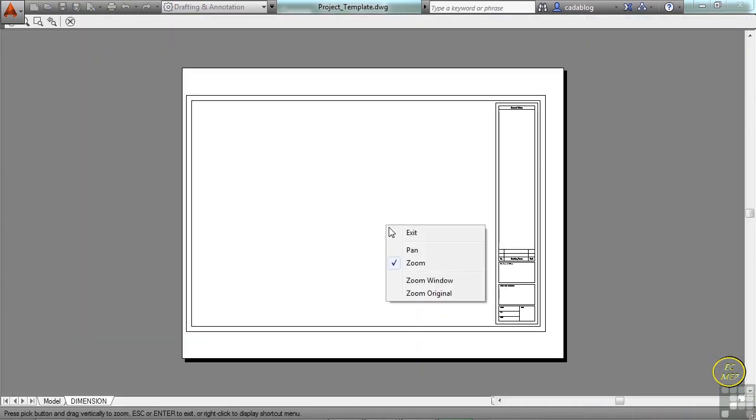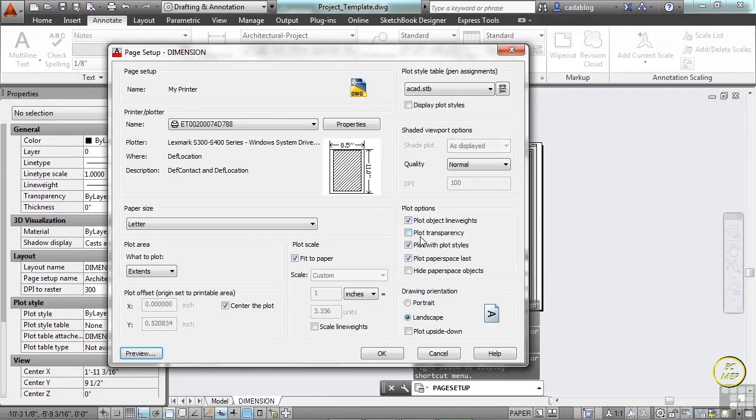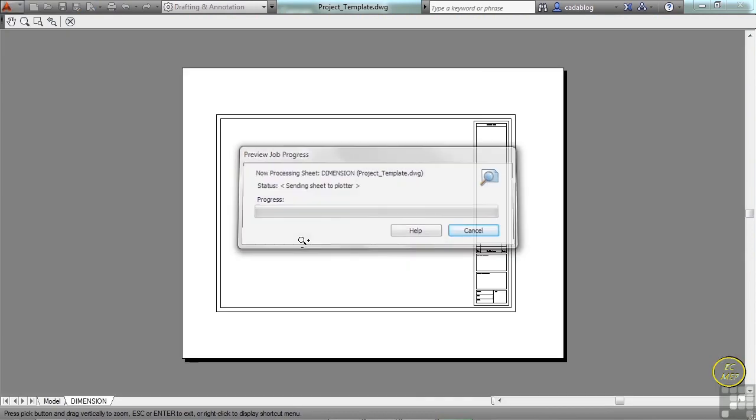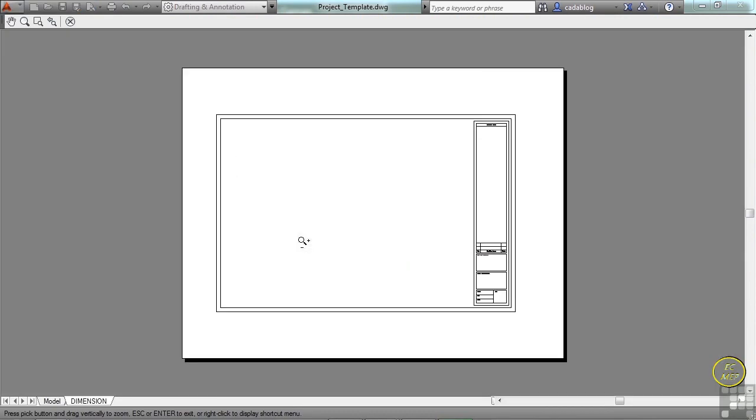It's not a perfect scale factor whatsoever. I admit that. But for what we're doing, it's okay. I can click on this fit to paper and then put in a scale, say 4. That will fit, as you can see on my preview. And it's a good scale that I can use, a factor of 4. So I can now put a scale on my drawing and scale some things, though I'm probably not going to want to because this is a real big reduction in size. It's a reduction of 4, 25%. So it makes it difficult. But that's okay.